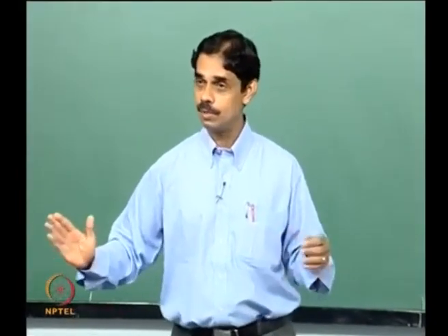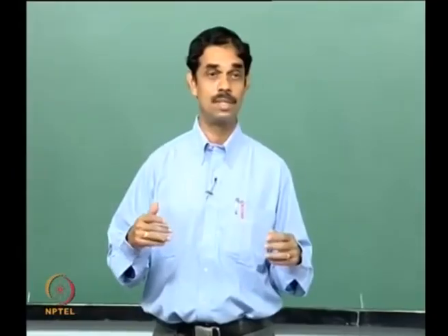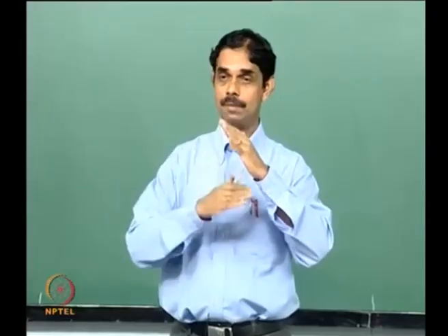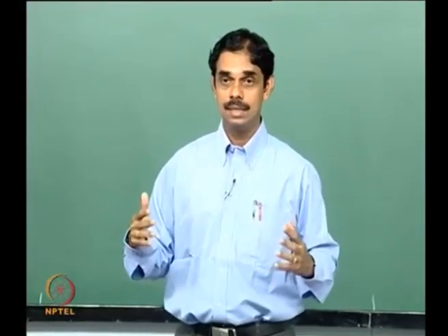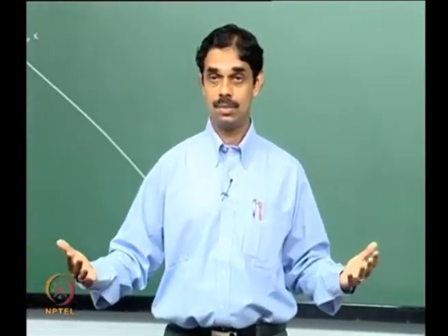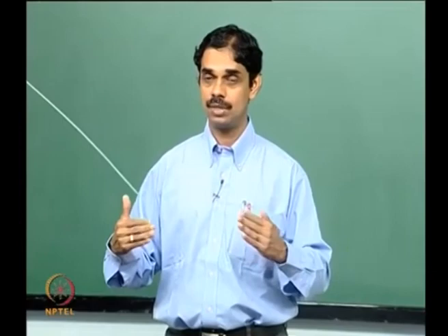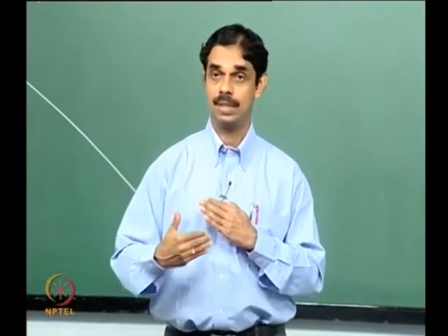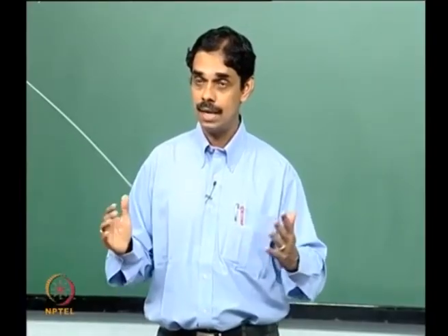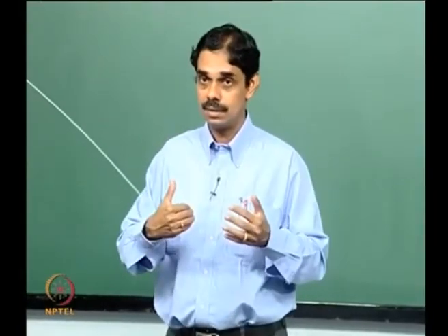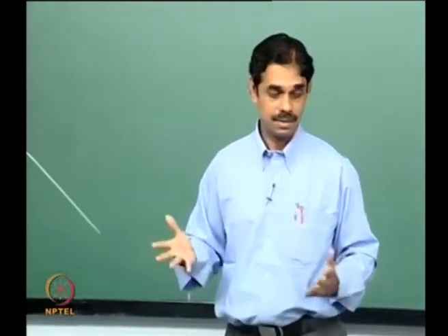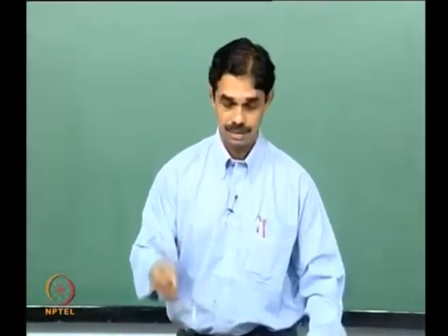So that means we are talking about a moving flame front, but if you light up a Bunsen burner flame, you will see the flame nice and standing like this. So as Vishnu says, the flame speed corresponds to the consumption rate of the reactants. So you have flame speed which is being balanced by the velocity of the mixture. In other words, you have a certain rate at which reactants are consumed, and as long as you supply as much as it is consumed, then you will have the flame front standing. Okay, this is clear, and that is how we are getting it in a Bunsen burner or something like that.